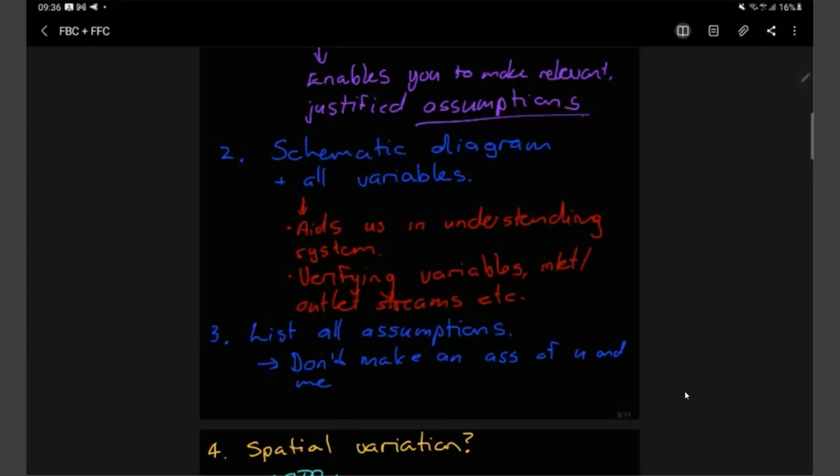But in the event of an electrical heater, there's no physical moving thing that is your final control element. In that case, a solid state relay, which is an electronic device with no moving parts except for some flip-flop stuff in a microprocessor or integrated circuit, is basically your final control element, which executes the commands of the controller, basically just switching the element on and off at a rapid rate.